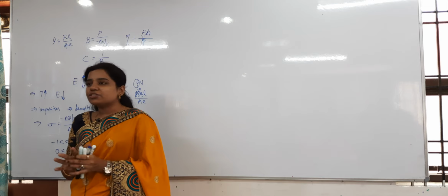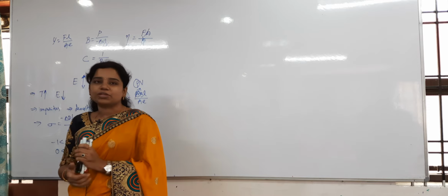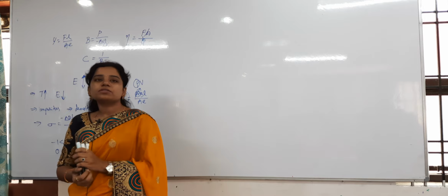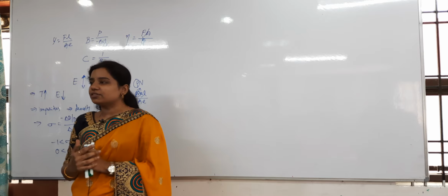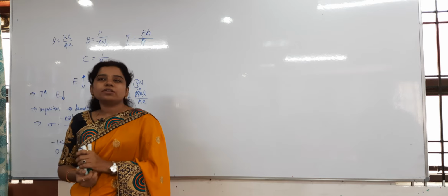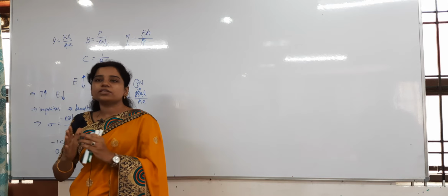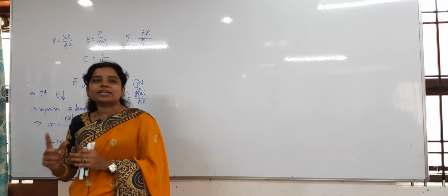Elasticity is there, but stress is not directly proportional to strain, so we call it the elastic limit. B to C, what happens? The yield point: it loses its elastic nature, so we call it the yielding point. Then C to D, what is happening? For a smaller stress there is a longer strain, that is a permanent set, otherwise ultimate tensile